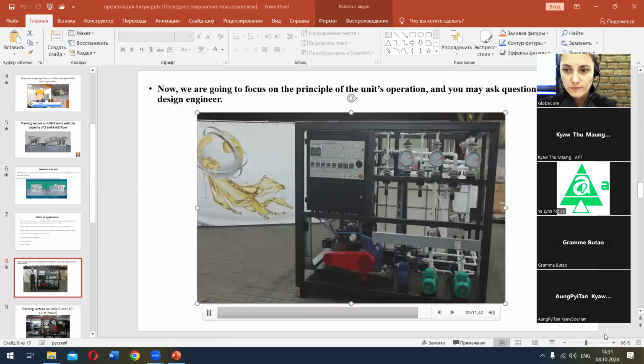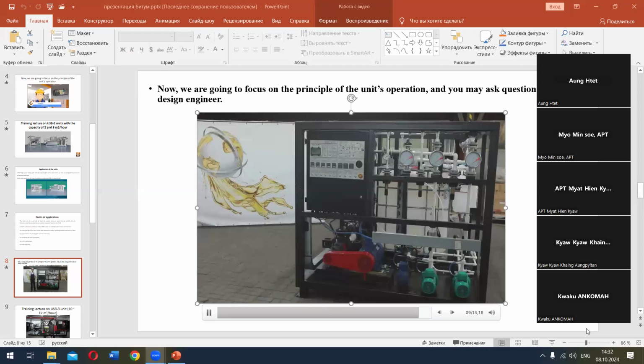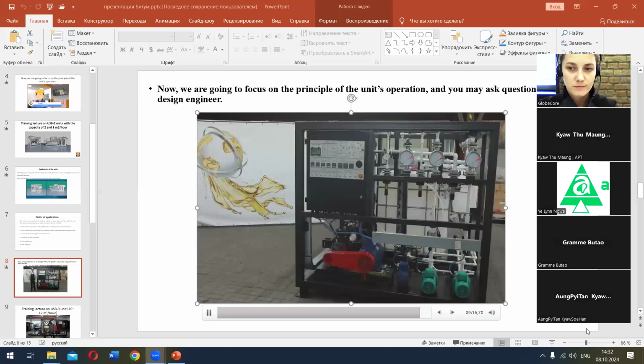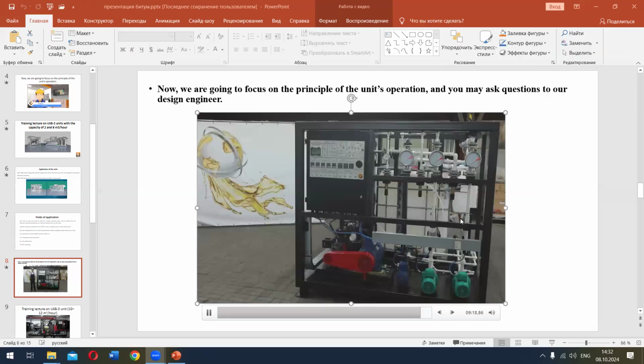At the end of this video, I would like to list the advantages of this unit. A wide range of formulations for the product manufactured, a good quality of the product manufactured with little time consumed, ease of operation and maintenance, compactness. All the bitumen pipelines, the mill, intermediate components have a thermal oil heating system, which is the mildest heating method. Another design advantage of this unit is the use of hydrodynamic mixers, which makes it possible to mix liquids at each stage.